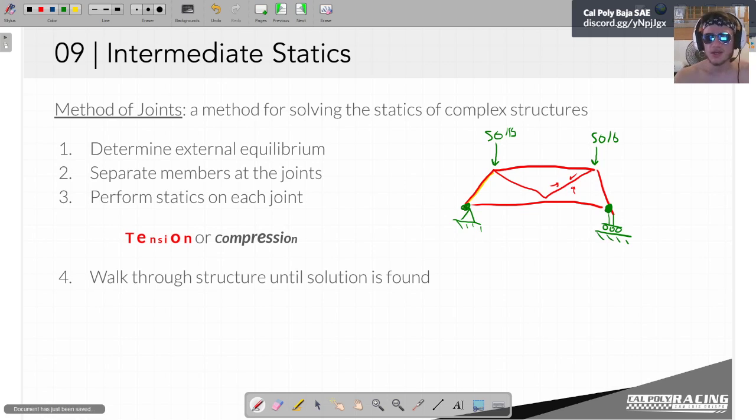Because if you think about it, if this wasn't pinned, if this was maybe a sliding joint, or if this joint here was something else, then it might just be that the bridge moves. If it's not attached at one of the abutments, you're going to go right into the water down here. So we need to figure out what our reactions are on anything external to our problem.